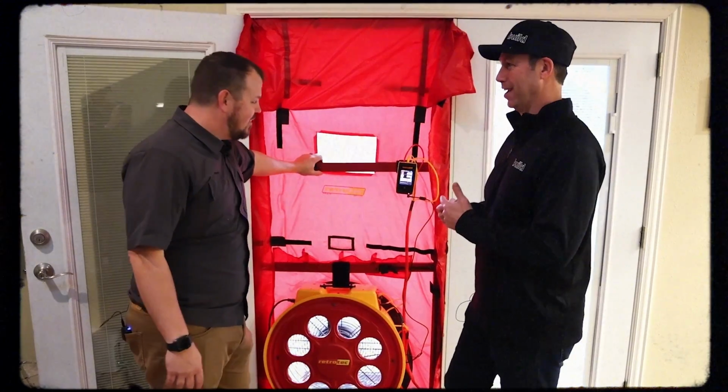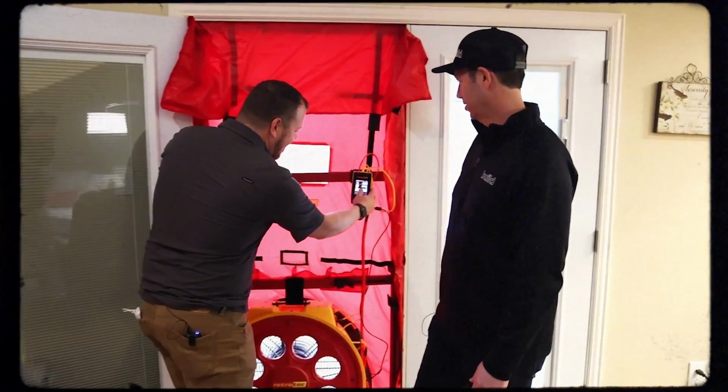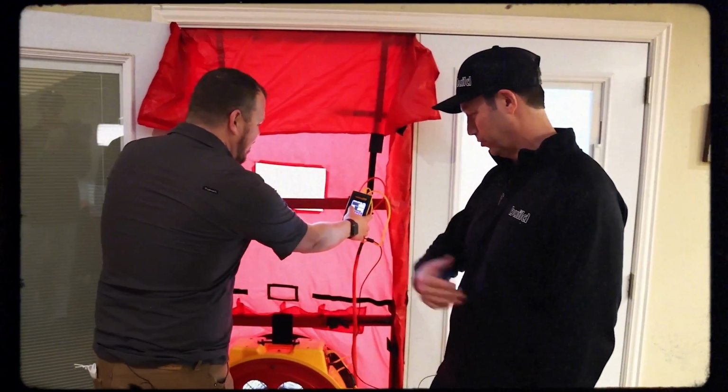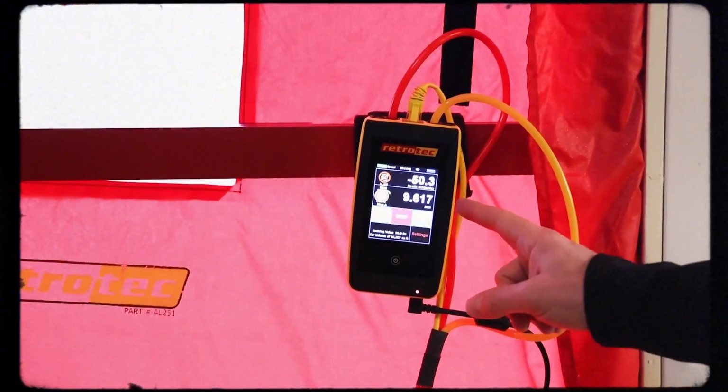It's incredible. And, you know, we can now test for it, right? There's this thing called the blower door test where we put a shroud on one of our open doors. We seal up everything. We put a fan in there. And then we measure the amount of air that we're running out of the house or pushing into the house. We can do a positive or a negative test, and we'll get into why we would want to do that. But we're measuring that flow across there at a certain pressure. For a residential blower door, we're typically at 50 pascals.